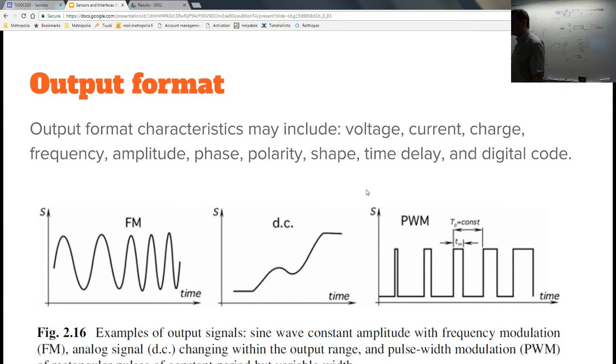And capacitance, if you have capacitance and you have inductance, what do you have there? You need just the excitation, and you have an oscillator, feedback and excitation. And basically you can measure the capacitance based on the frequency, fundamental frequency of this LC circuit.